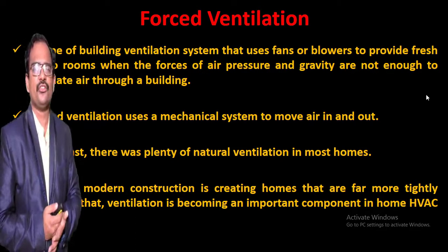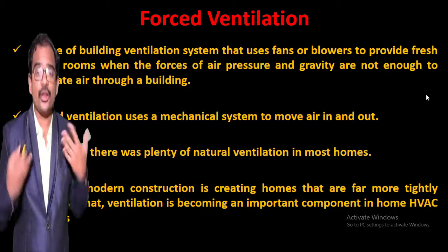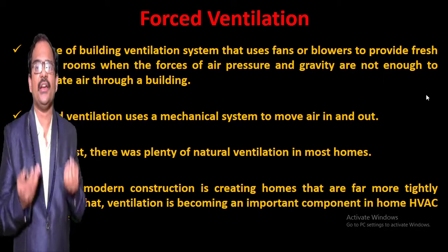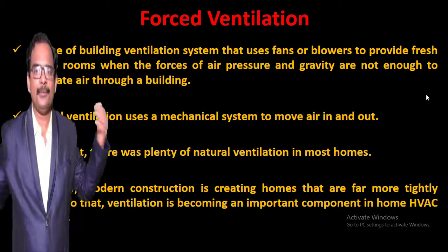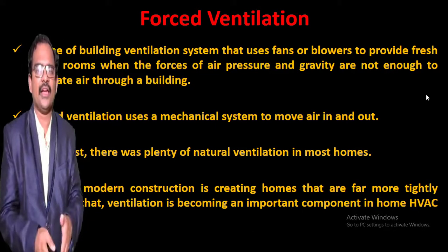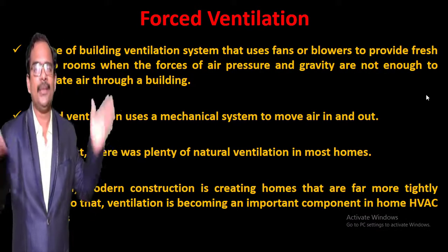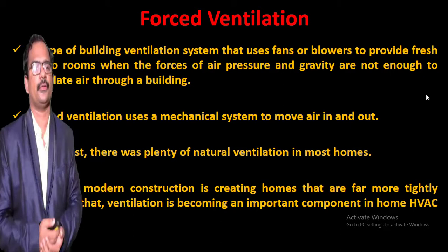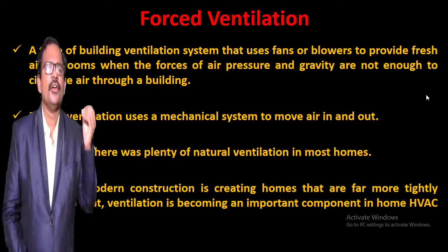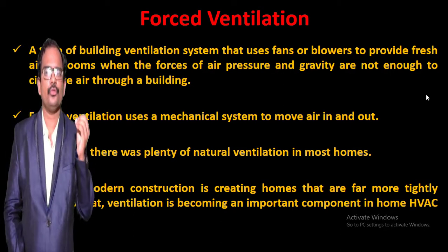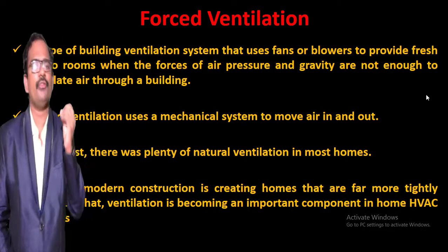And this forced ventilation system will provide that extra gradient in pressure and temperature, so that the air will be brought into the home as well as removed from the home by means of fans or blowers, right? So forced ventilation uses mechanical systems to move air in and out of a closed space or home.